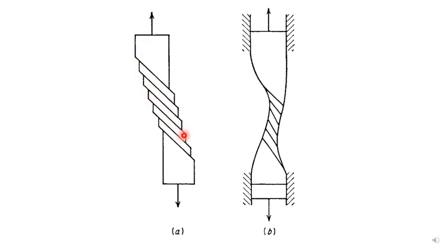As we mentioned in the last slide, slipping occurs in any slip plane and direction, any slip system that is neither horizontal nor vertical, at any angle with the horizontal. So in this illustration, the axial force causes a slip in this direction.